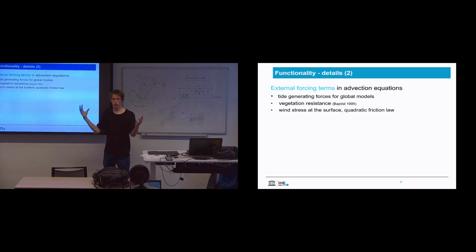And that also has wind fields covering the entire globe. So you can not only calculate the tides, but also storm surges and so on. You can add cyclone tracks in it, and you can calculate the effect of it. Or you can actually do this with ensembles. So you can throw in 1,000 cyclone tracks and see what the probability distribution of a storm surge is.